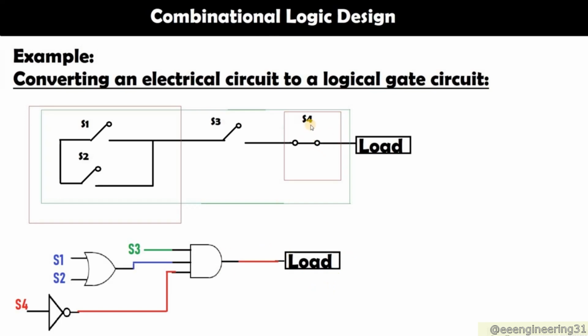Now let's take a case where the NOT gate is having a 1. So if we energize this, it's going to be open, and the power here should be cut. So if we put 1 at the S4 right here, it's going to be 0 because this is a NOT gate, and this 0 will propagate till here. So we have now a 0 at one of the inputs of the AND gate. Well, this means that there will be no conduction of power because it's an AND gate, and all of these need to be 1. So this circuit is actually working as expected.